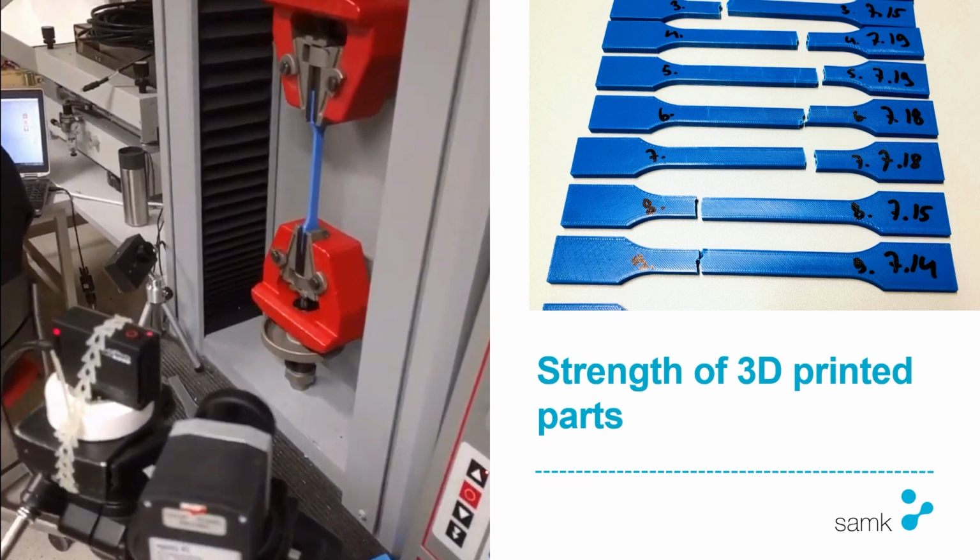You could easily snap these parts with your hands, and the parts that were printed like in the image shown on the right, in that direction, you couldn't break them in half with your bare hands if the infill was 100%. So it affects the strength of the part considerably.